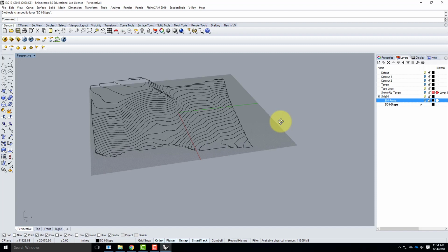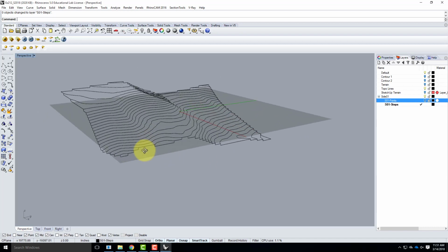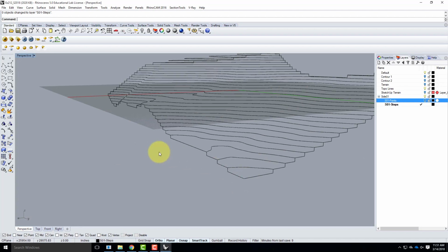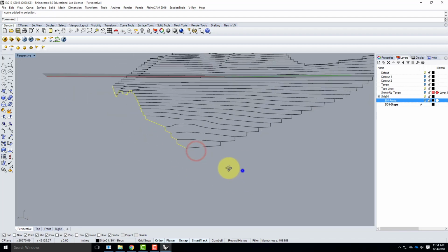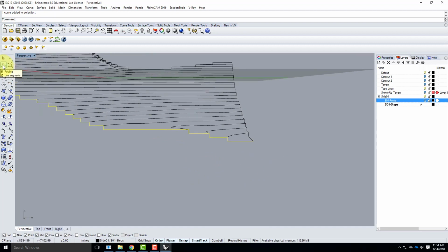So I'm going to take it to the next step, and I'll start slowing down my process a little bit because you guys will be having to do this part today in all likelihood. So when I start thinking about this, each one of these sides needs to be a side to support my contours. So I'll find whichever side is the lowest. So it looks like this point here is my lowest point of all the points. So I'm going to start there with a polyline right there at the corner.